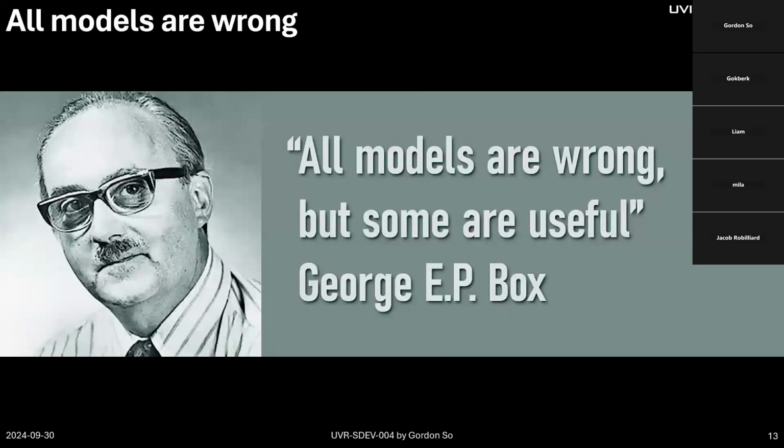And the last thing, a really important mindset, is that all models are wrong. A CFD solution will never be correct in a sense, because you're making a bunch of assumptions too. For example, you may have a flow, but sometimes you assume no turbulence. So there's already a model that you apply to your problem. This is very important because it is basically the mindset of the whole CFD: trying to get a good enough solution with good enough required time.